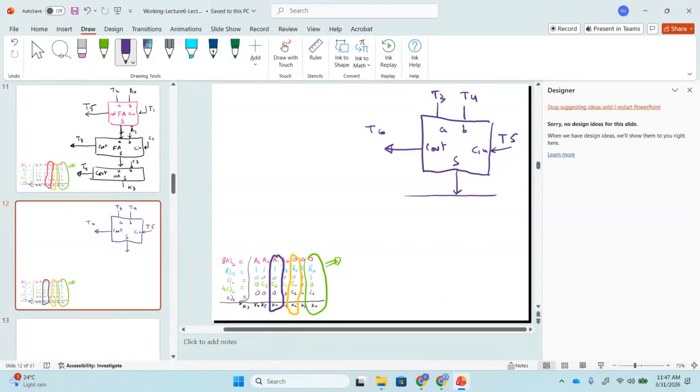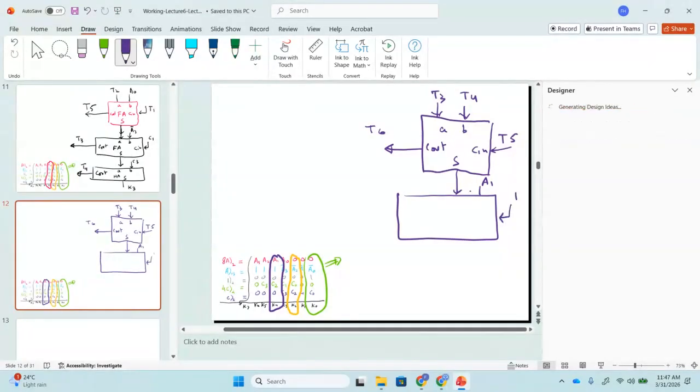Now we need another adder. Can you see here? Now we need to add what? The sum is from here, and then we need to add A1 here, and then we need to add 1 here. Then we have S, so we have T7 now here. Since we have a 3-bit adder, this S will go to another adder.